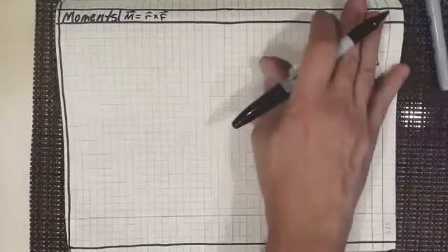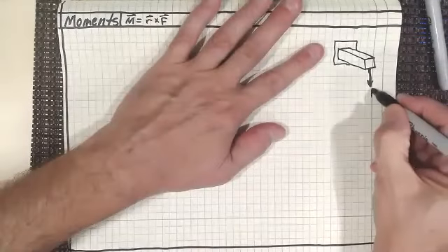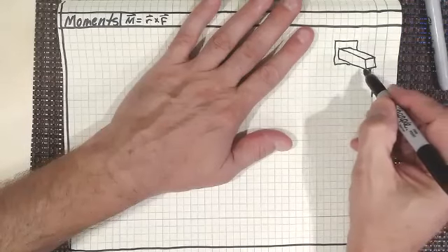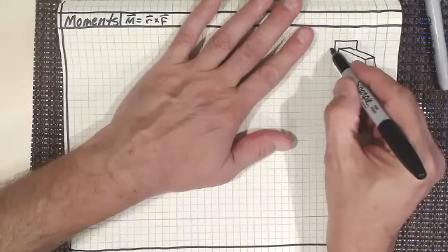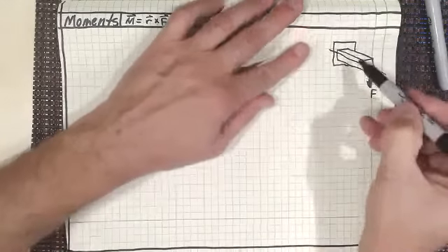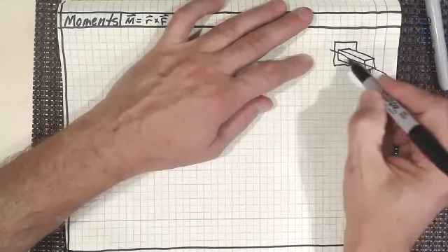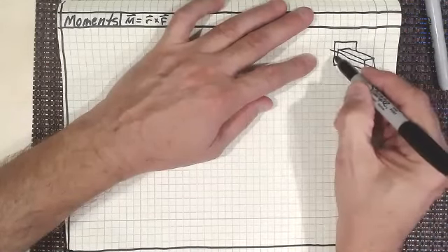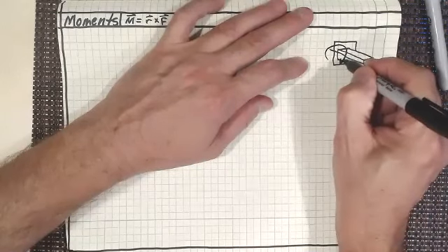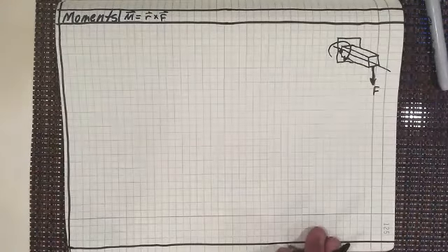Doesn't quite show up on the TV screen as it does here, but we've got a force going down, and I think everybody can see that if I was to draw an axis through the side, this force is going to cause this beam to deform in this way. And so really what we have is an applied moment right at that point.